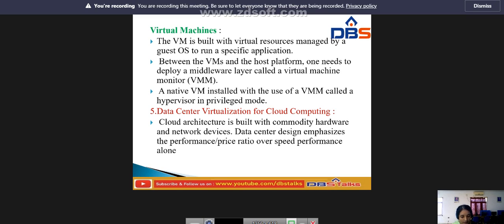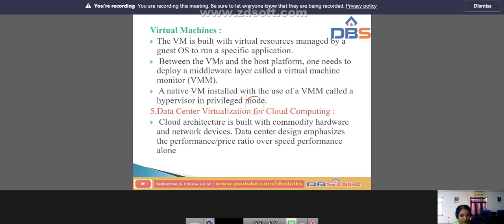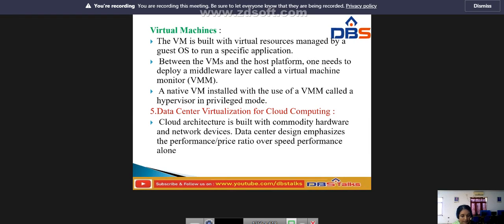The 2009 IDC report says only 30% of data center cost goes toward purchasing IT equipment such as servers and disks. 33% is attributed to the chiller, 18% to the uninterruptible power supply, UPS, 9% to computer room air conditioning, and the remaining 7% to power distribution, lighting and transformer costs.